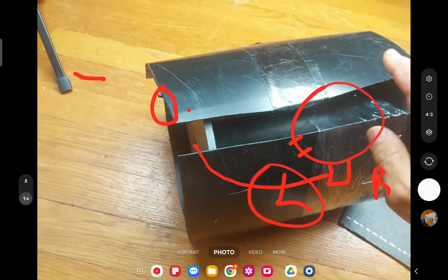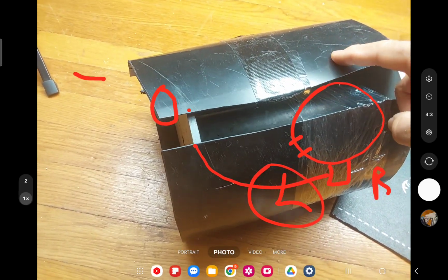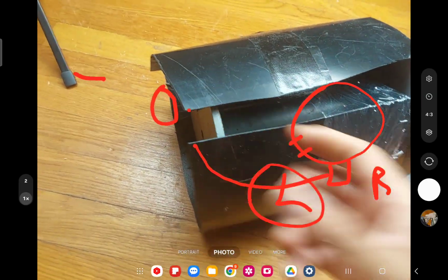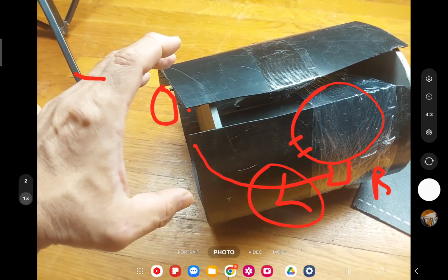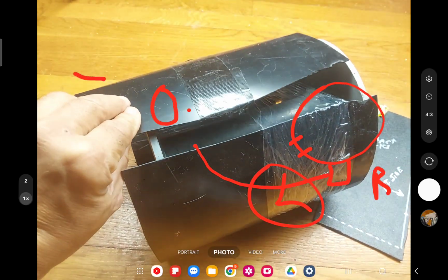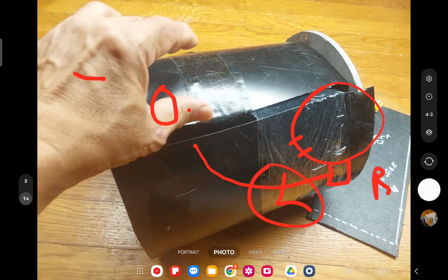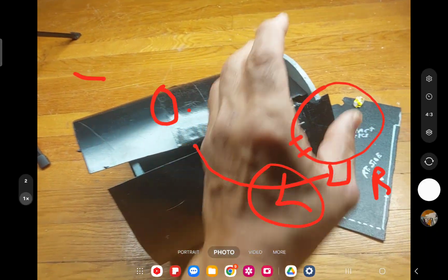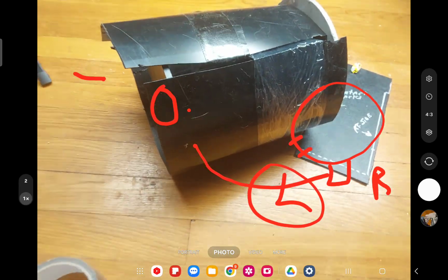So we're buckling back here somewhere, not here, buckling here. So folding in, going in, that allows the end cap to release from here and rotate in and drive. This also, as it buckles in, gets driven down because of the pressure. This guy comes sliding across the rest of the carbon fiber, tearing apart layers, grabs the tank, shoves it in the back, breaks off the end cap, the interface